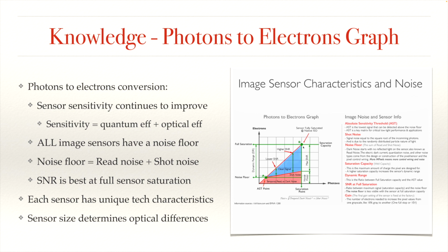Here is what we call the maximum SNR and the maximum noise level of this sensor. We talked about SNR. If I have more exposure, in other words, more photons, then I have a higher saturation point on the sensor. What is the advantage? If I increase my saturation, I increase my SNR, the signal to noise ratio, so the clean signal versus the noise part in the signal. In this case, I will have less visible noise.